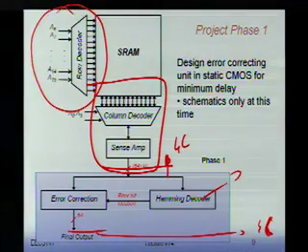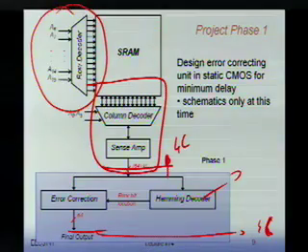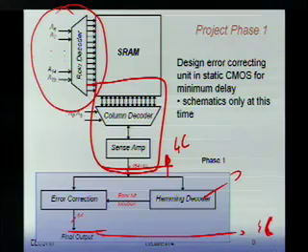So the only thing we'll not let you do is basically the SRAM cell. We'll give you an SRAM cell that you can use. Because doing a good SRAM cell takes quite a little bit of tricky kind of layouts, type compression. You want to make your cell obviously as small as possible. So area of the cell is very important. Okay? So that's the idea.